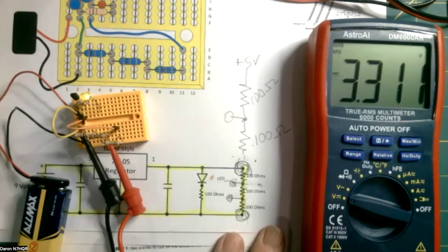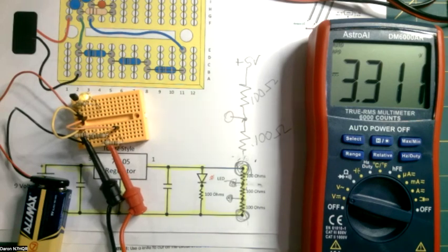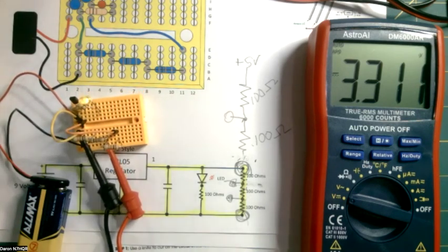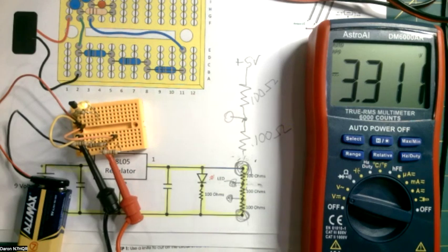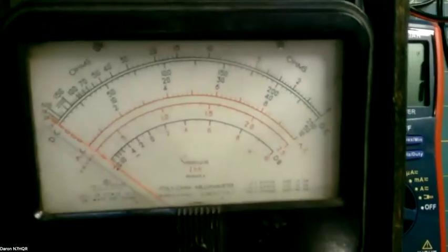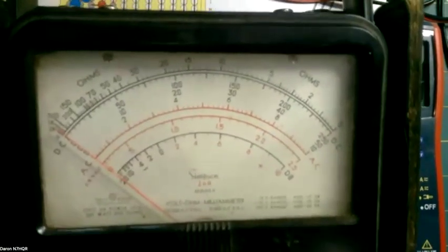It used to be, before the digital meters, that we used VOMs, where voltage, ohm, milliamp, ammeters, and it was just a meter movement. And when you stuck it in the circuit, it would load the circuit, so it would change the values. If you were looking at a really high resistance area and you stuck your ohm meter in there, it would change everything. And with these digital meters, they're typically 10 million ohms impedance, which means, oh, an old Simpson. Oh, that's beautiful. The old ones used to be rated in so many thousand ohms per volt, right? Correct. That's the old school way of doing it.